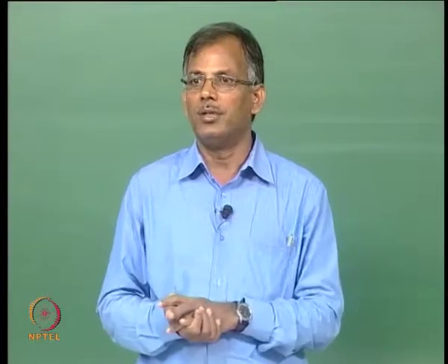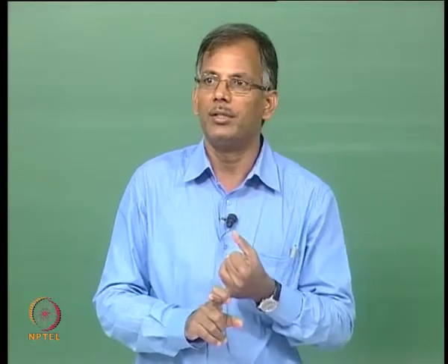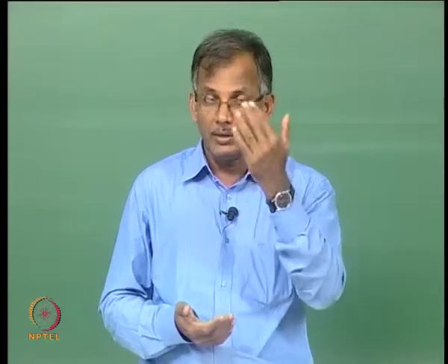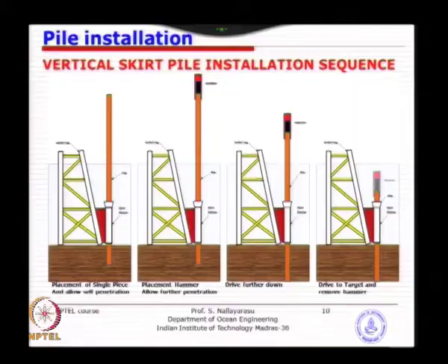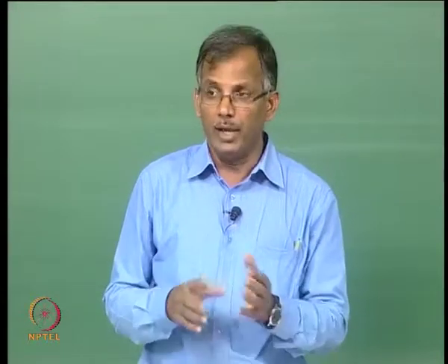The project is gone. So, that is why you have to see the criticality of borehole investigation, making decisions to use a particular hammer, and monitoring the driving time; it is very important. After making all the effort to bring the jacket, if the pile fails during driving, you have just no remedy. That is why pile driving becomes one of the most critical parts of the whole project. In a few cases it has actually become like that, two of the piles just could not be driven any further, with premature refusal as well as buckling.